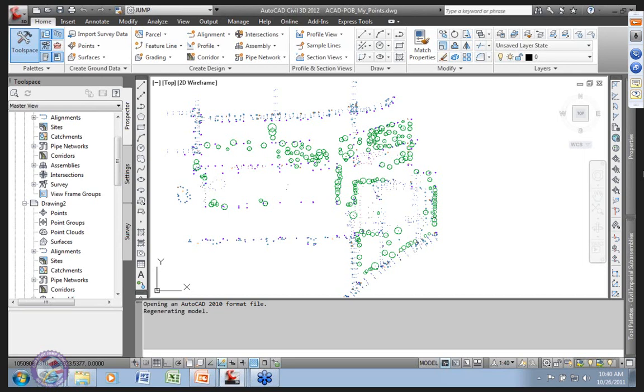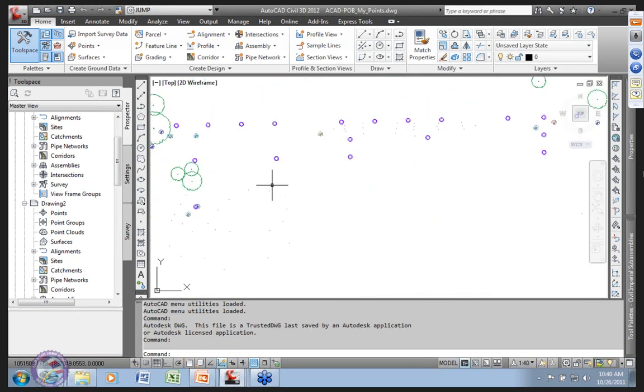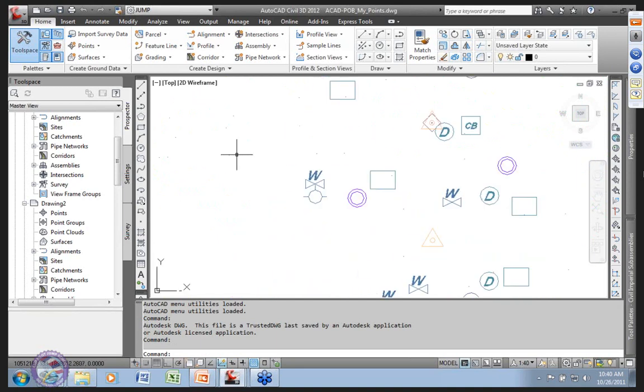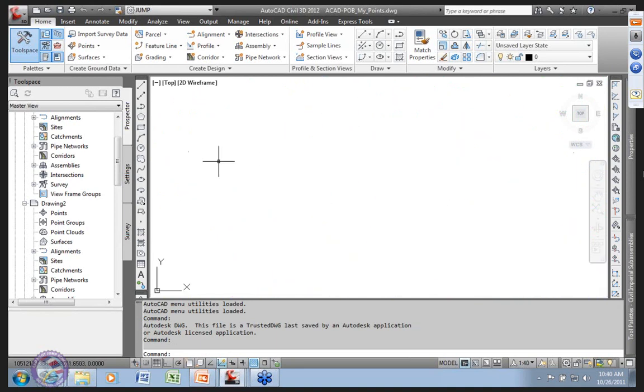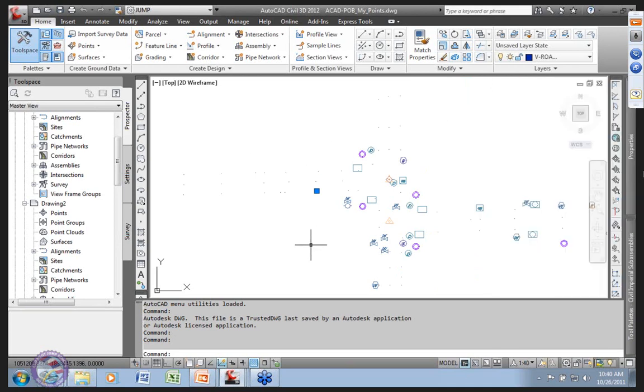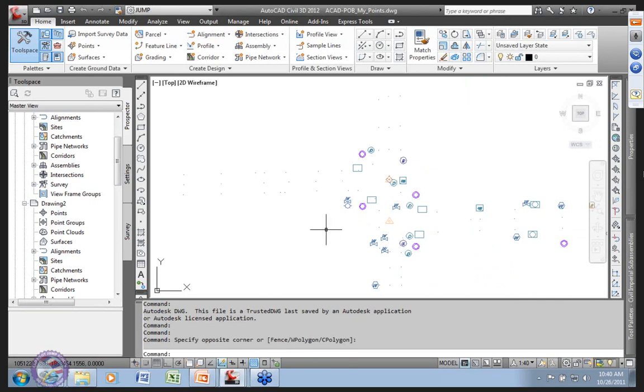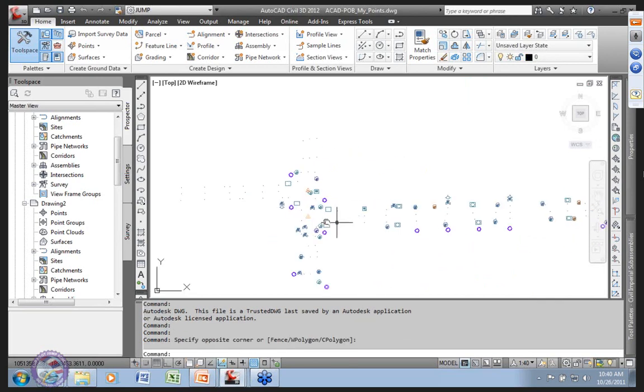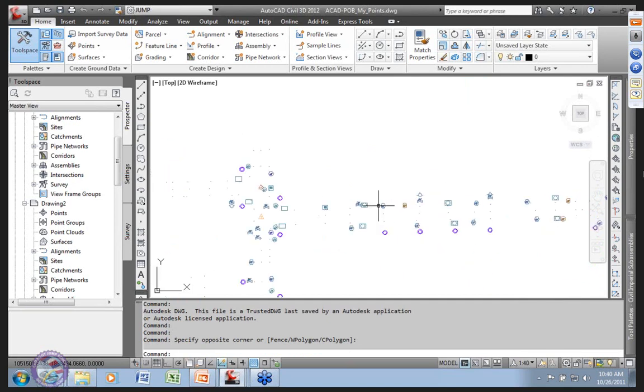And if you open this points drawing, wonder of wonders, things look exactly like I wanted them to look. And one of the things that AutoCAD and the whole deal is trying to do is make sure that graphically you get out whatever you told it to get out. Now I had those V boxes, those V points, and they end up not exactly what I wanted. In fact, what did I end up with? You end up with a block reference. So everything is wrappered in a block, and if you had labels, they would show up too, all wrappered in this block.